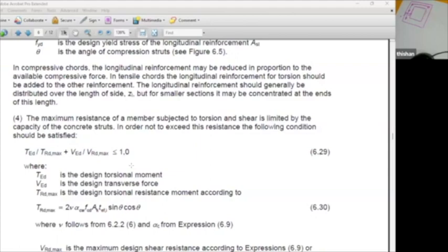The moment you go for square sections, you'll find flexural shear drops, and torsional shear also will drop, and we have a chance of satisfying this particular condition. Now these are long equations, and the ideal way is to show you how to do the calculation with the example.